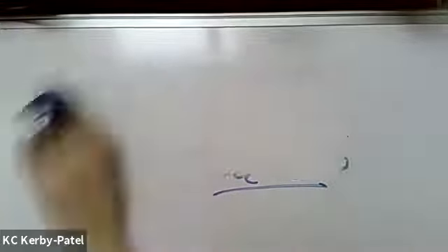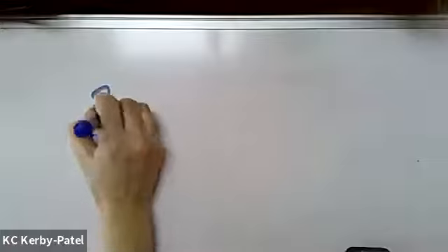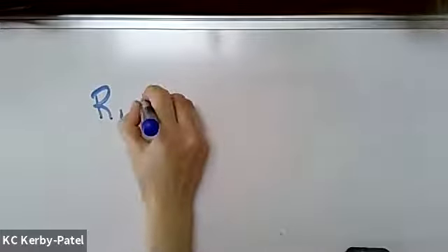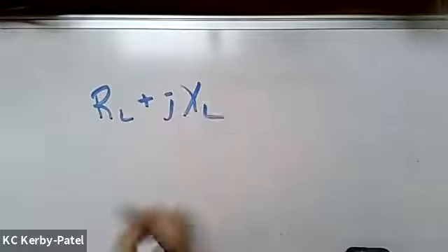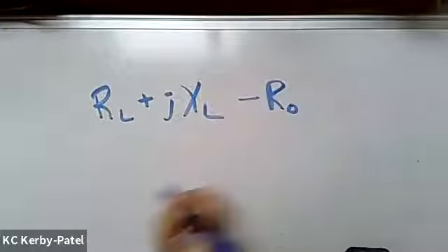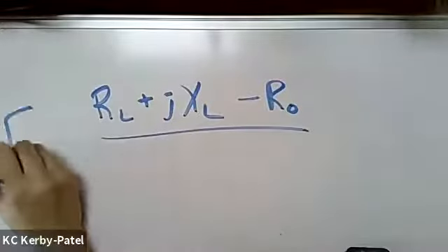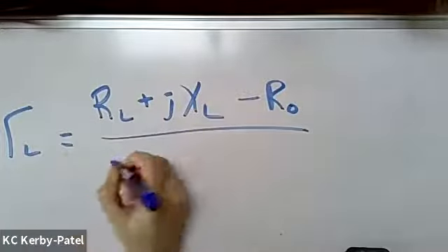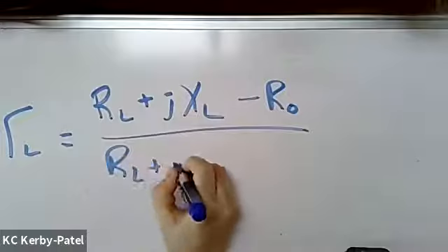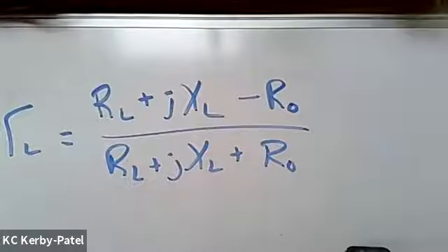So in that case, I'm going to split the load up into R plus JX for the load, minus R0. Here's our load reflection coefficient. Then we have RL plus JXL plus R naught.